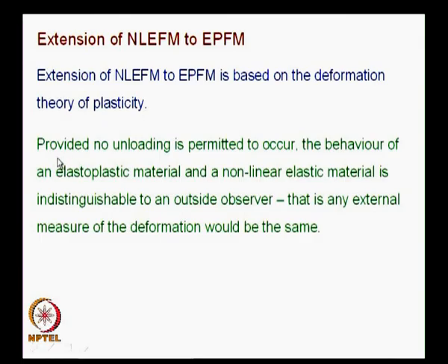So, you say provided no unloading is permitted to occur, the behavior of an elastoplastic material and a nonlinear elastic material is indistinguishable to an outside observer. That we had seen, the loading and unloading paths are same when you are nonlinear elastic, but if unloading is permitted in elastoplastic material, the unloading path is different. So, now you do not permit unloading.